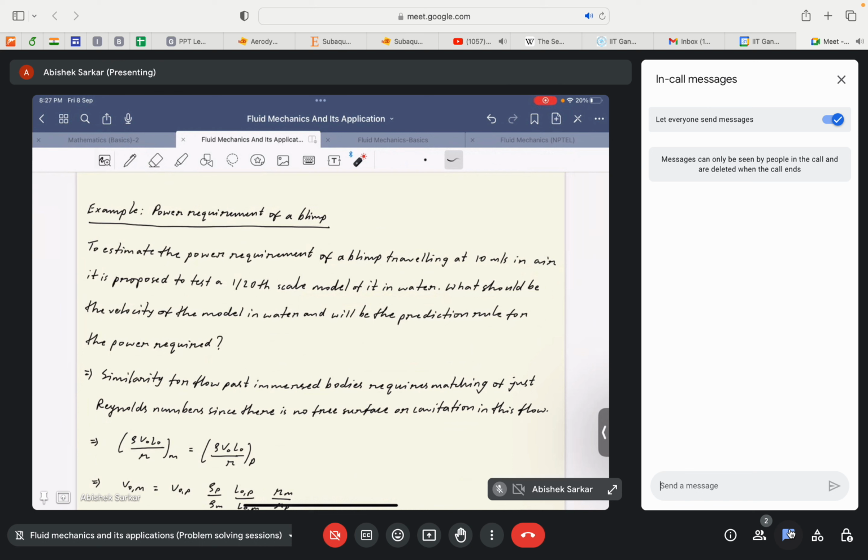But moreover, you will see, as a mathematical conclusion while comparing non-dimensional numbers, that if we had kept the fluid the same, there would be a certain jump in the values of other parameters, because the density remains constant and there is a huge discrepancy in the dimensions of the prototype and the model.